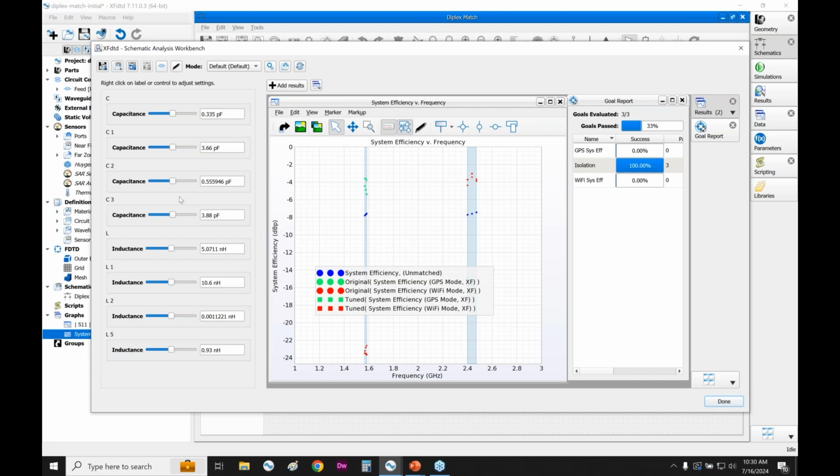And so what this allows you to do is, like an optimizer, is good, it's useful, but it's not always going to produce the exact result that you're looking for. And you as an engineer have some knowledge on how your matching network applies. And so you can say, yeah, the optimization got me in the ballpark, but I know that my capacitance value here is going to affect my schematic a certain way. And so then you can come in and manually tune these.